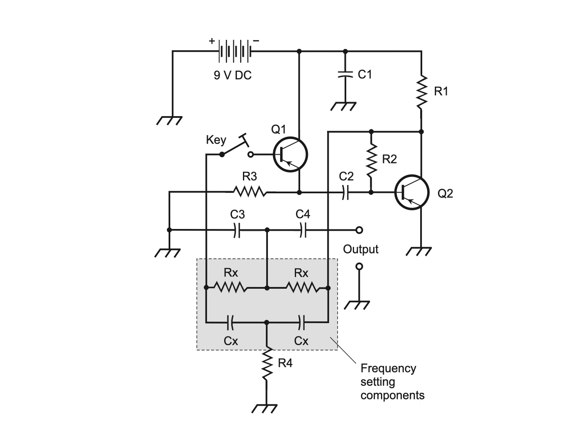This particular circuit is called a twin T oscillator because of the T-shaped configurations including the resistors marked RX and the capacitors marked CX. The twin T oscillator produces an AF tone that's pleasing to the ears, and that also occurs at a predictable and stable pitch, or frequency. The AF signal in this circuit goes around and around. That's how oscillation happens. We can start pretty much anywhere and follow the signal back to the same point.